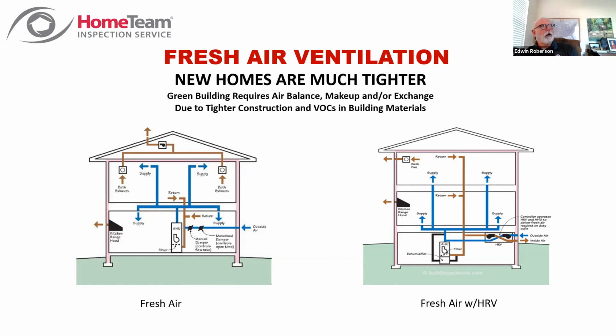If you follow that ductwork, you'll see that it goes over typically to a sidewall or to the roof in the attic, where you draw air in, and then you follow the ductwork out of that, and you'll see it goes into the return duct. And we show those in the report when we do our inspections, so that a client can see what they've got. But that's how you make up air in a controlled, conditioned manner in a very tight house when you're running things and you just need more air in the house.